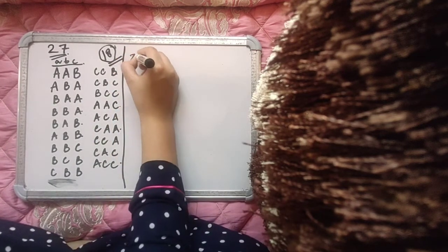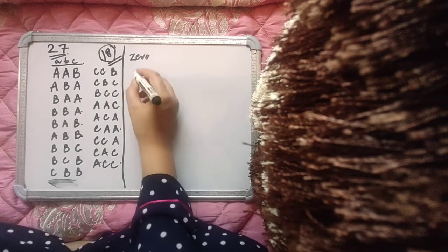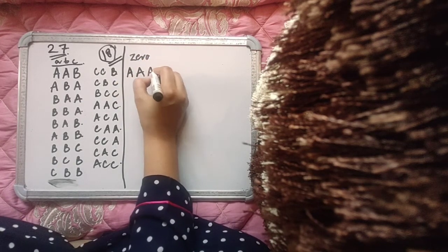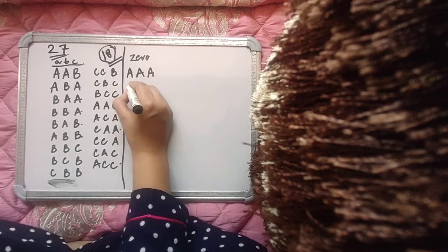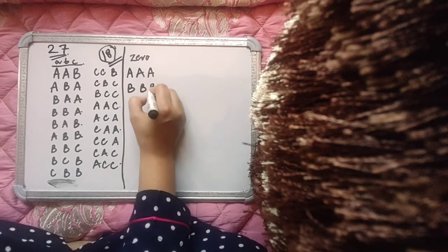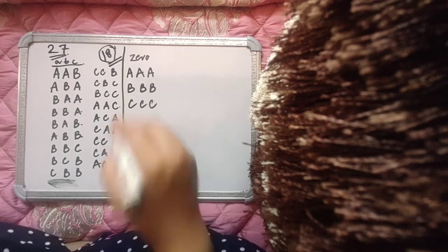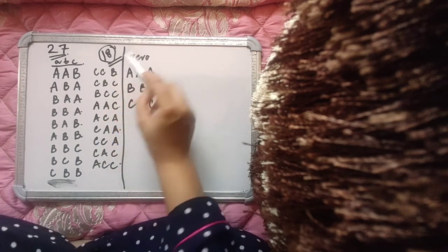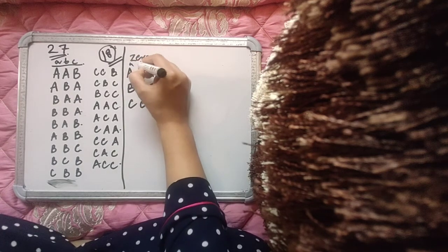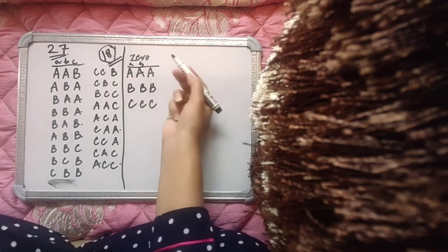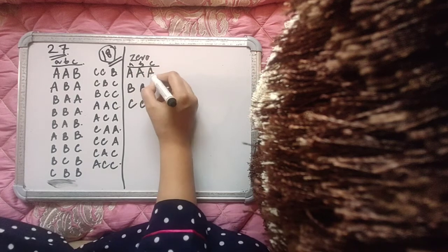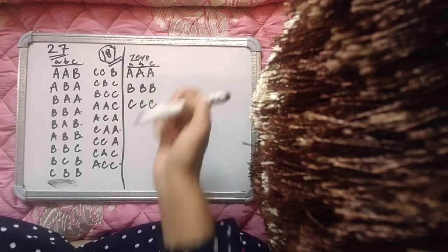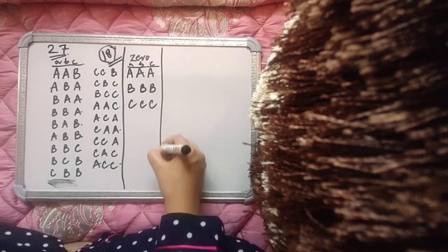Then you also have the zero states. The zero states are one in which the same input phase is sampled at the output, AAA at the output, or BBB at the output, or CCC at the output. Obviously, in this case, the output line voltages will be zero, because line voltage is what? VAB is A minus A, that is 0, or VBC is B minus B, or C minus C, that is 0, and VCA is also 0. So these are the 0 states.